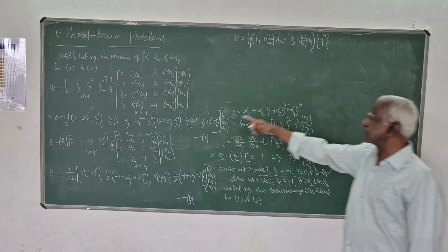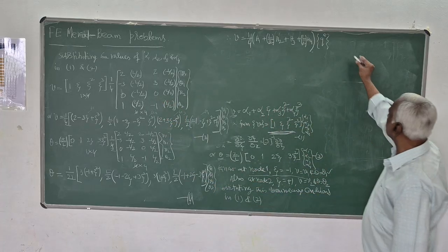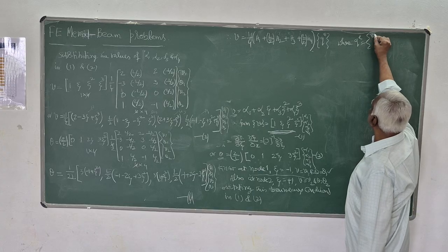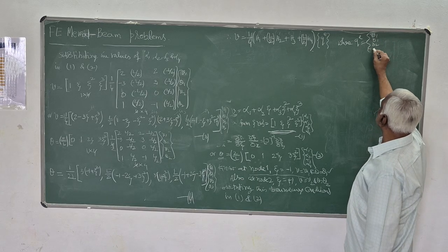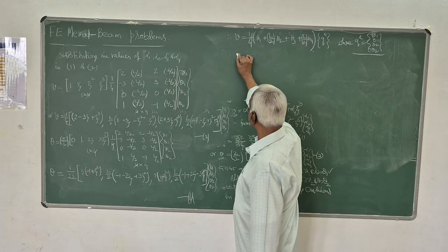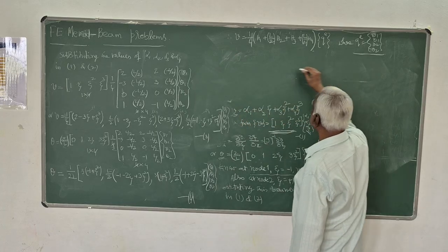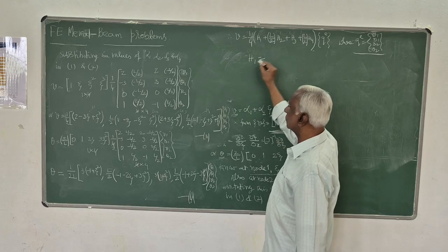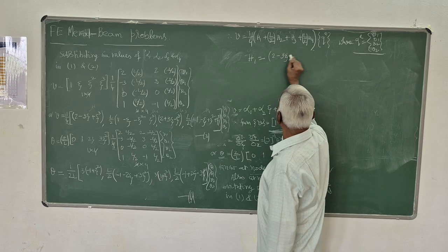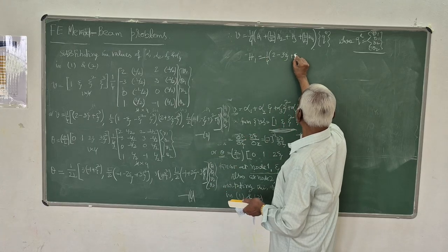QE is nothing but V1, theta 1, V2, theta 2, the displacements at the two ends, a 4 by 1 vector. And where QE is equal to that, H1 is equal to 1 by 4 into 2 minus 3 xi plus xi cube.